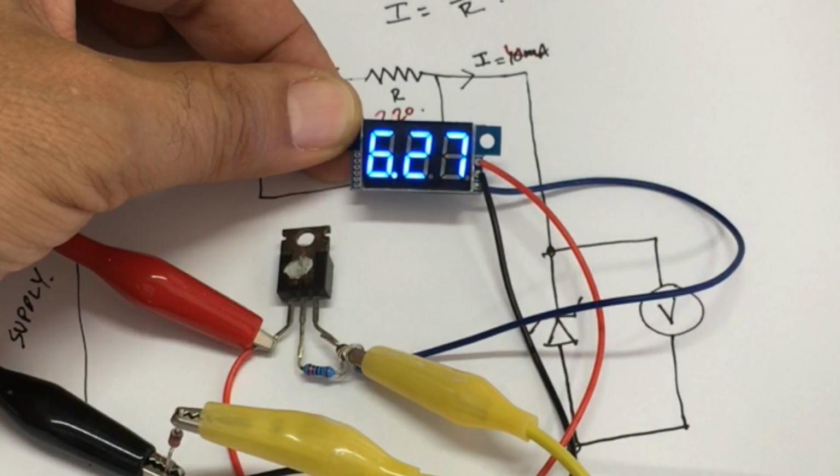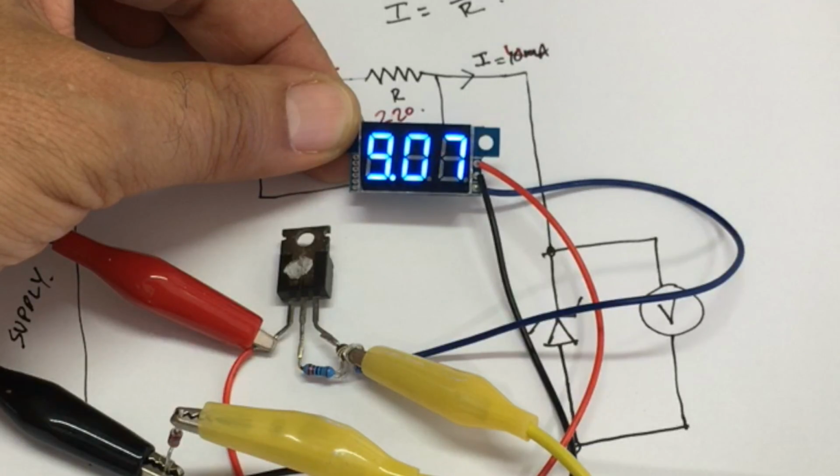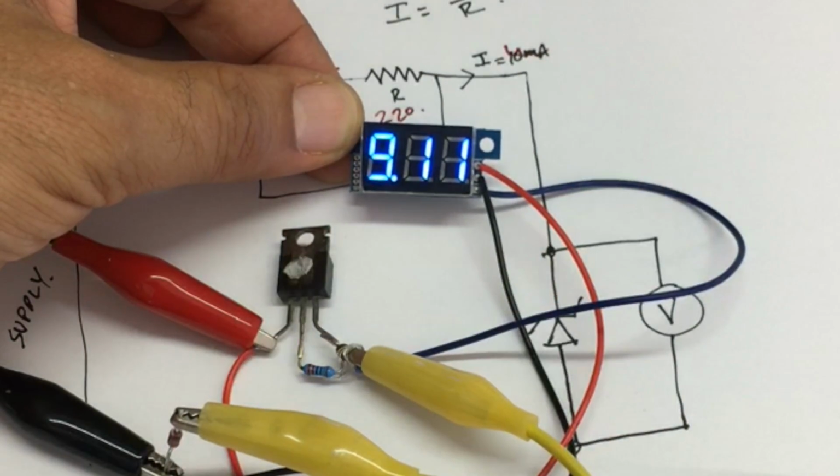So if I increase this, it's going up. I'm increasing the supply voltage, same way I did before. It's now on about 8, and we've got about a 0.6 across the LM317. If I keep going up, it's now at 9. Keep going up, and it's stopping, and I'm at 10, and I'm at 11, and I'm at 12. You see what happens? We've got exactly the same situation, and I'm going to put all this all the way up to 24 volts. It's at 24 volts, and my voltage there is 9.1. So I know that is a 9.1 volt Zener.